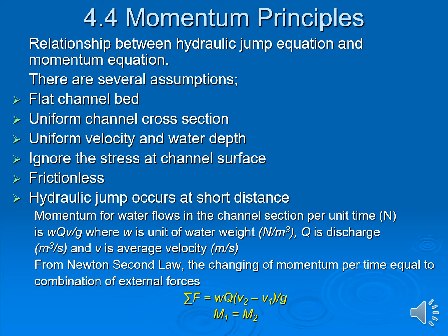These are the assumptions in the relationship between hydraulic jump and the momentum equation. There are several assumptions here: the channel bed must be flat, the channel cross-section uniform, and the velocity and water depth also uniform. Ignore the stress at the channel surface, it must be frictionless, and the hydraulic jump occurs over a short distance. And from Newton's second law, the change of momentum per time equals the combination of external forces. And we have mass in equal to mass out.